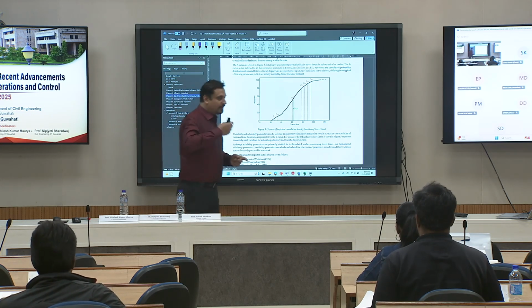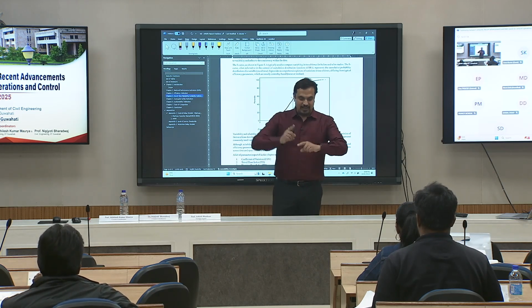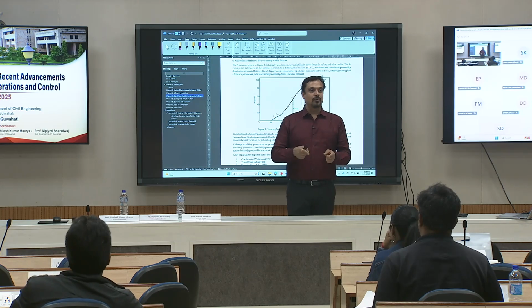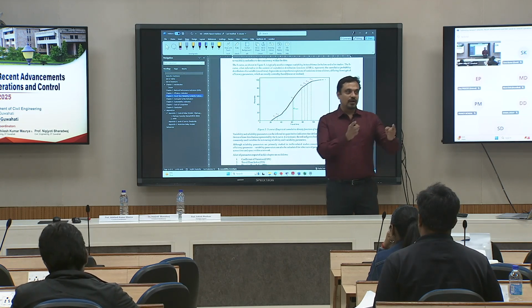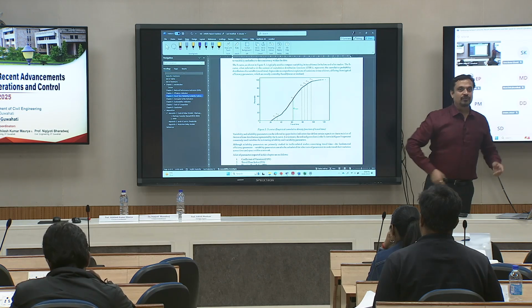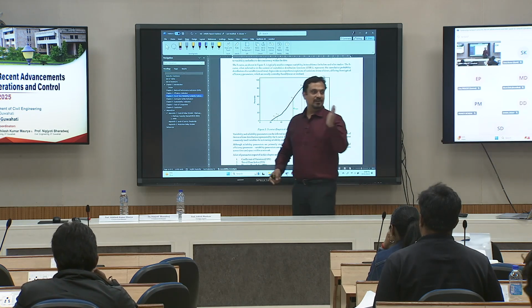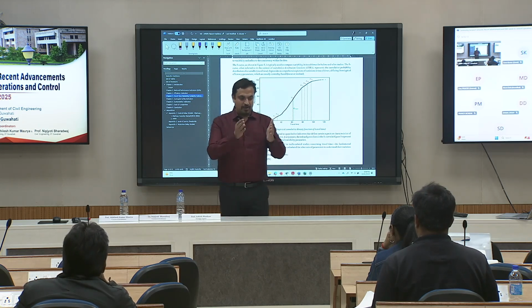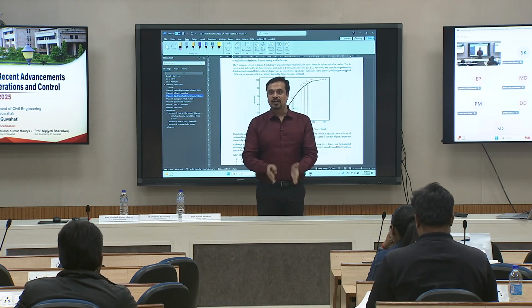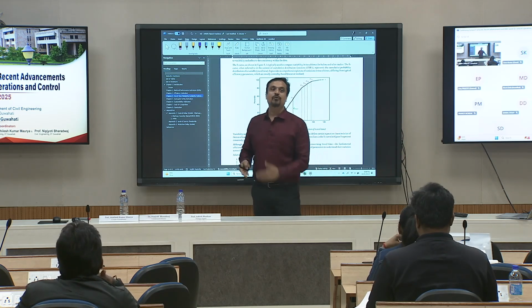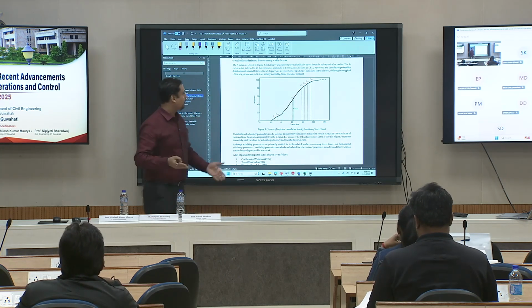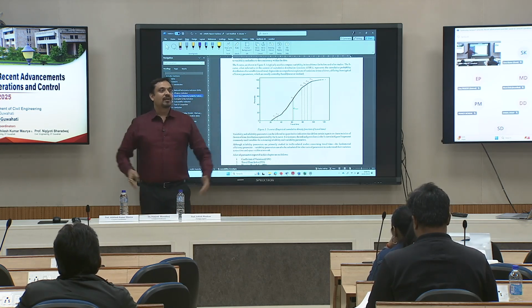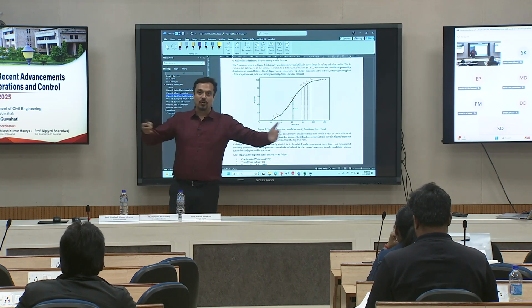Now note, I mentioned that from, let's say, 11 to 12 a.m. in the morning for that corridor, what was the average travel time over different time intervals for day 1, day 2, day 3, day 4, day 5. So we are talking about day-to-day variations on this one. So it's a whole spread we are talking about. If you get a travel time every 15 minutes, you have 4 data points for day 1. If you have, let's say, 10 such days, you have 40 data points. For those 40 data points, you draw the CDF plot. If you do it for the whole month, you have 120, or it depends how long you go, but you get the plot.